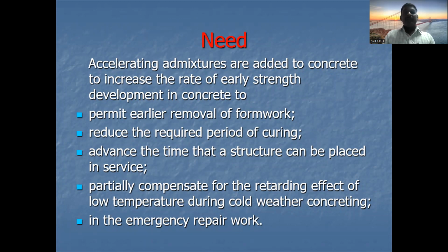But sometimes we are doing concrete in seawater, or underwater construction, and at that time it is necessary to set the concrete at an early stage. So for that purpose we are adding this accelerating admixture to increase the rate of early strength development of the concrete.